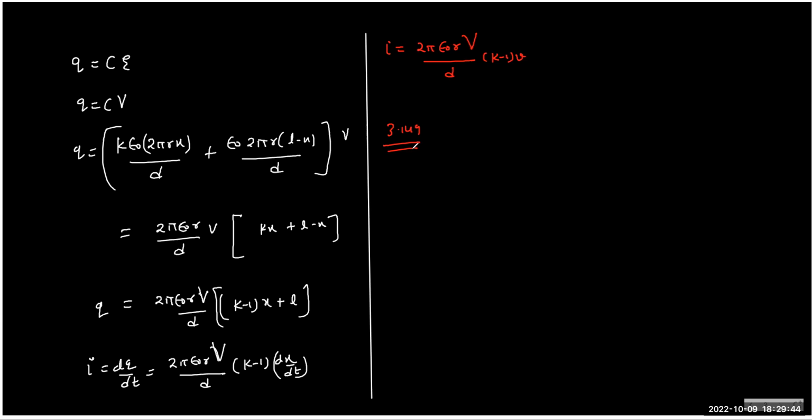At 0 degrees Celsius, the electric resistance of conductor 2 is eta times that of conductor 1. Their temperature coefficients of resistance are alpha 2 and alpha 1 respectively. Find the temperature coefficient of resistance of a circuit segment consisting of these two conductors when they are connected in series, and part B in parallel.